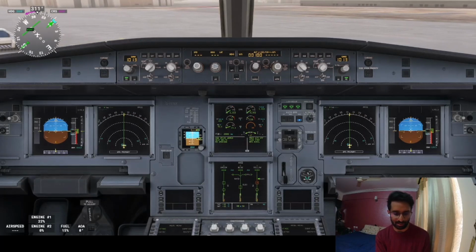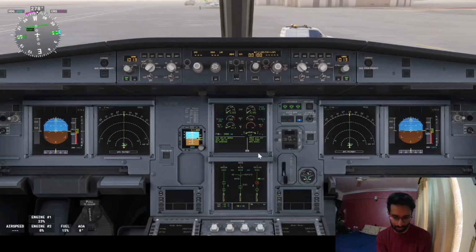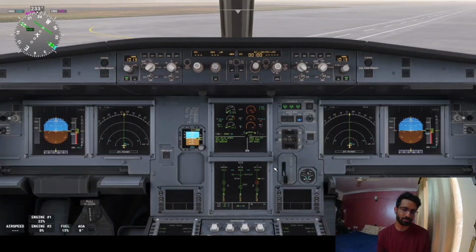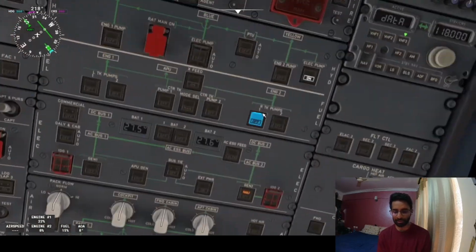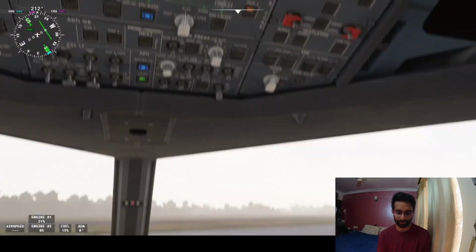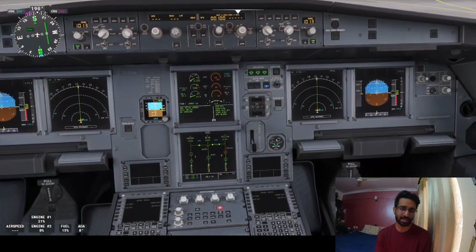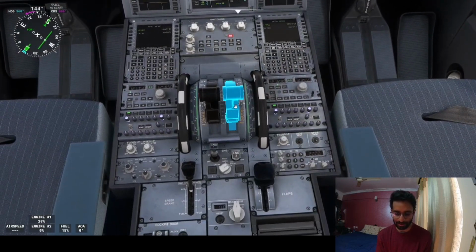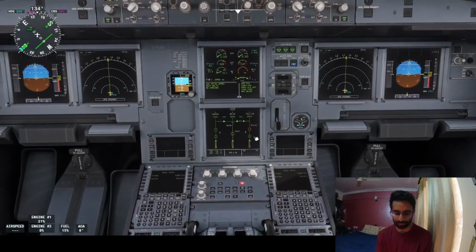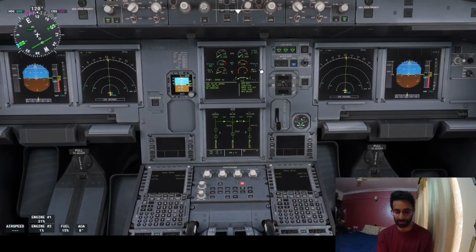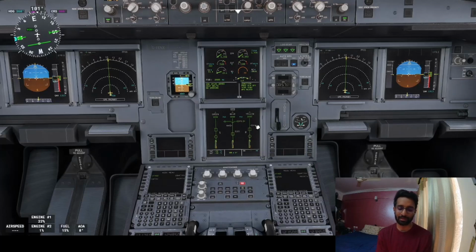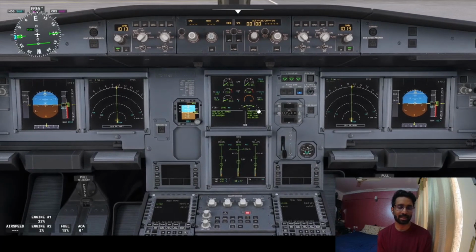Now let's say I am taxiing, disregard where I am going, there is a car there, that's all not going to happen in real life. So you taxi out. So is the PTU working now? No. Now the moment we start the second engine, we turn off the electric pump. We need the bleed. So now the PTU starts running as per the third logic. Now we'll have the second engine started. The PTU self-test will run for a while because see, the pump has kicked in, but the PTU will run. That is the self-test, and after that the pump will stop. Second engine is starting, and then we will continue with our normal SOP.